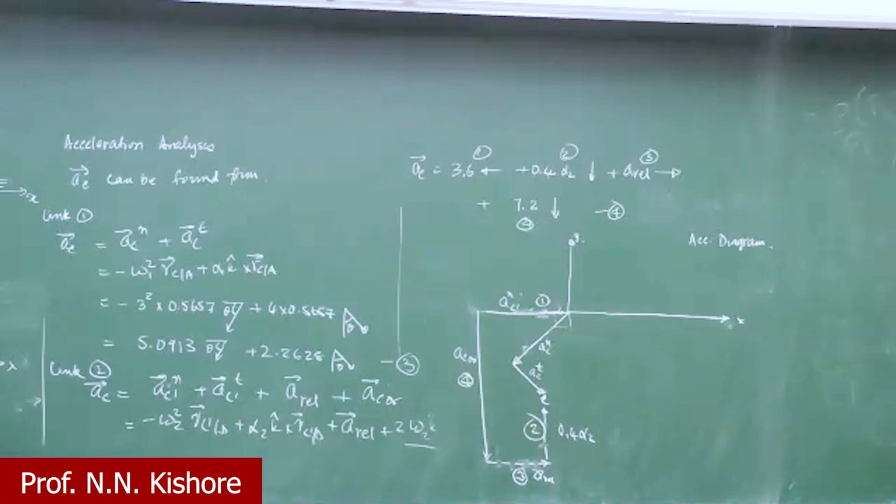that this is the X and Y and this is the origin here. So this point here also happens to be A and B. The velocities of, this is the image of AB. In fact, this ABC everywhere, whatever you have, these are the velocity images of various points. And similarly here, C prime to C will give you the relative velocity. So obviously this also tells you that C is moving in the rightward direction. Okay, so that way you can really understand the problem much better.